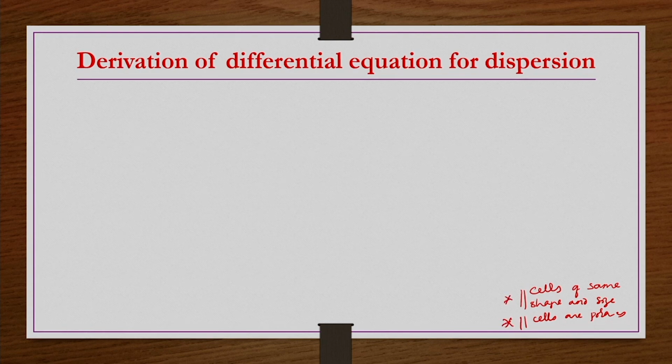In general, whenever we do the momentum or mass balance for a given geometry, we take the walls as solid, no-slip walls. But now this is a packed bed, which is like a porous media, so we have to take the cells as porous, right. These two are the important, essential assumptions in this derivation.